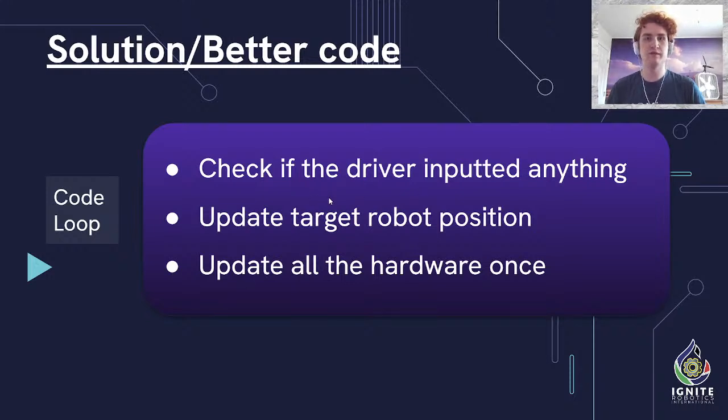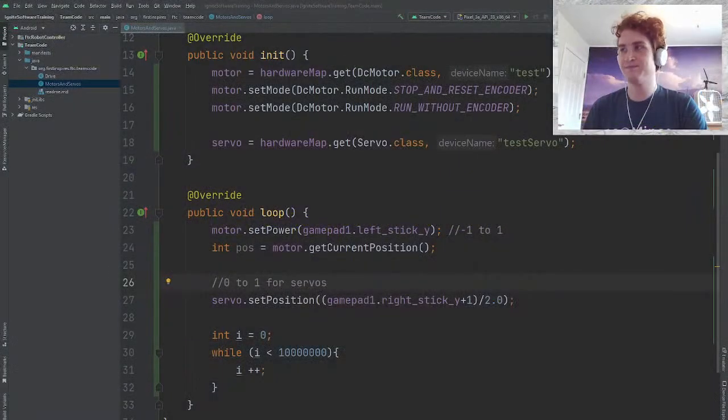Specifically, when we do stuff like this with pressing buttons, we need to know something called rising and falling edge inputs. When you press a button, oftentimes you want something to happen the moment you press that button and not after you let go, etc. So we're going to go in and show how that works.